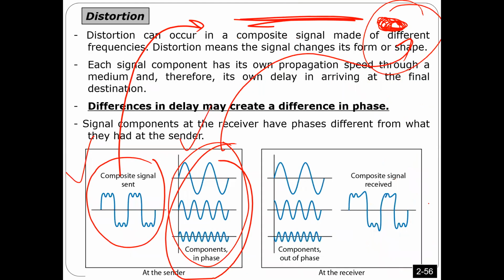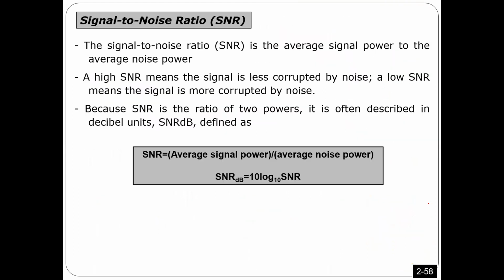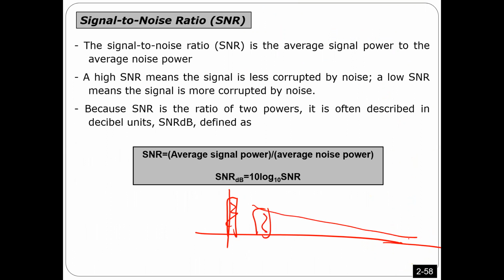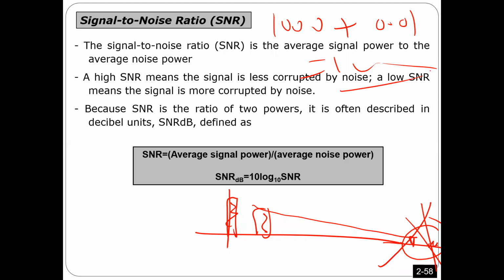That's why if you look at the frequency domain, you see the first frequencies have big impact. But as we go here, you find these ones have very little impact. So that means I may not need this component. Yes, there will be some distortion in the signal, but it's not severe. It's still okay, because these frequencies have very little amplitude. If you have 1,000 plus 0.01, I can still say it is 1,000. Makes sense?